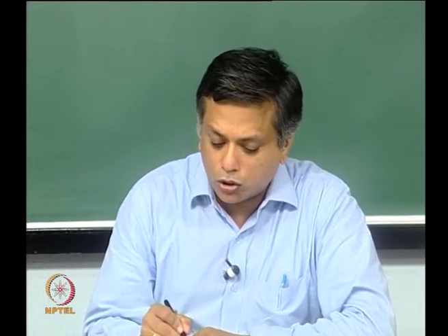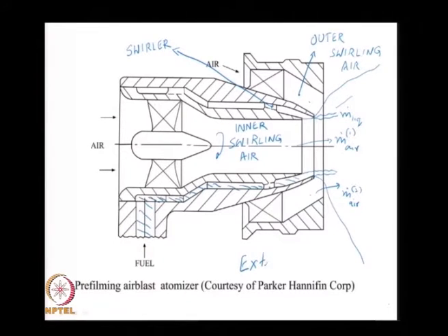This is also an example, we are still in the realm of external mix air assist atomizers. This particular design is patented by Parker, and it goes by the name pre-filming air blast atomizer, because you are essentially creating a film.